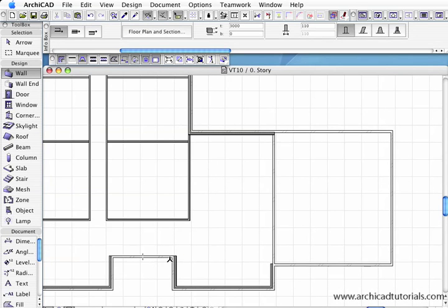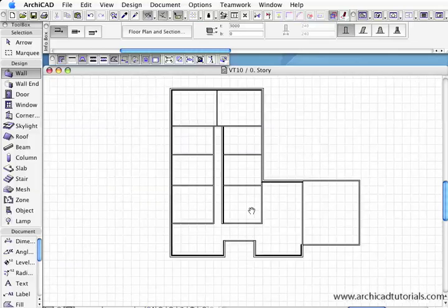And I'm just going to do that through the project. Even internal walls, I can quickly swap between walls and pick up the properties of one wall and move across to other walls within the building. And this works for all objects, all walls, and it's a very quick way of changing the properties throughout your project.